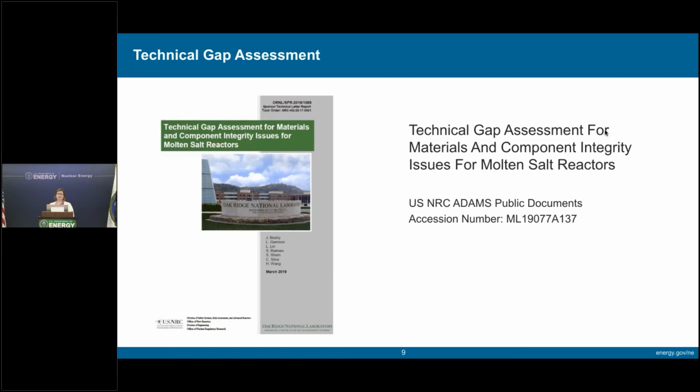So obviously we want to develop some new structural alloys that can have a better temperature performance than the 316 stainless steel. So this is the boundary. At 650, we already have structural materials that we think we can use. So any new structural materials will probably have to be greater than 650C. So it's between 650 and 950, and 950 we're looking at as a stretch goal. So somewhere in between will be what we're interested in, but more toward the higher temperature side.